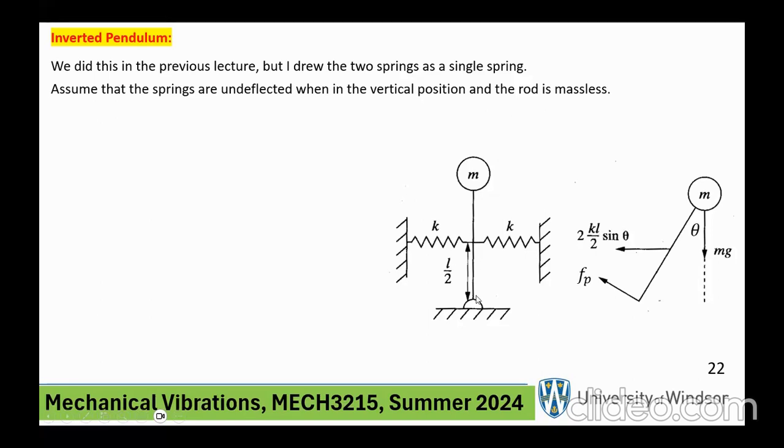See that if this vertical line tilts by the amount theta, for example, the length here, which is L over 2 times sine of theta, where this is the angle theta, will be giving you the stretching or the compression.